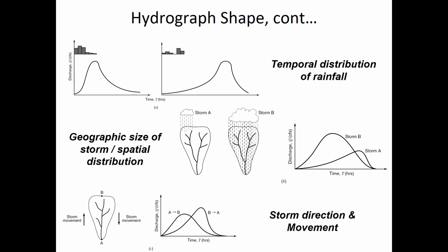Whereas in contrast, when the storm was going from A to B, as the clouds were moving over the watershed, the rain was wetting the stream, so that when the water finally did get to location B and those drops started making their way towards the outlet, all of the abstractions had already been accomplished. And so it's kind of like the travel time was less when the direction was from A to B, even for the particle that first landed at B. So in the case of the movement from B to A, that raindrop that falls at B, maybe it took 30 minutes. But you put that same raindrop at B when everything else downstream is already wet, and maybe it only takes 20 minutes to travel instead of 30.